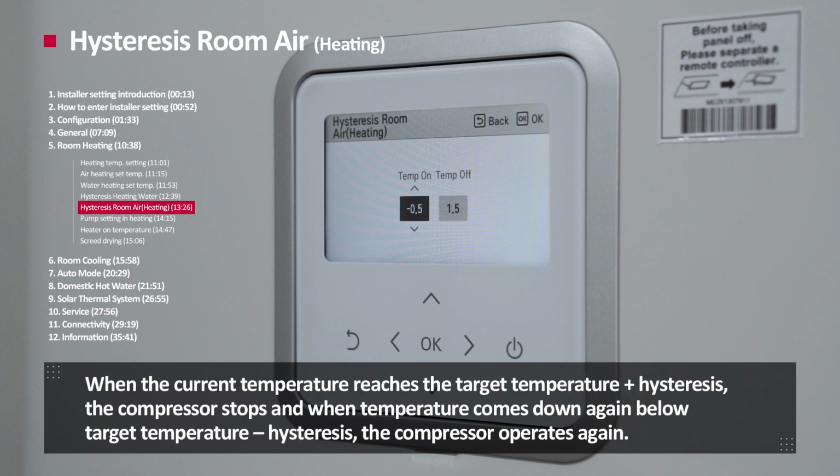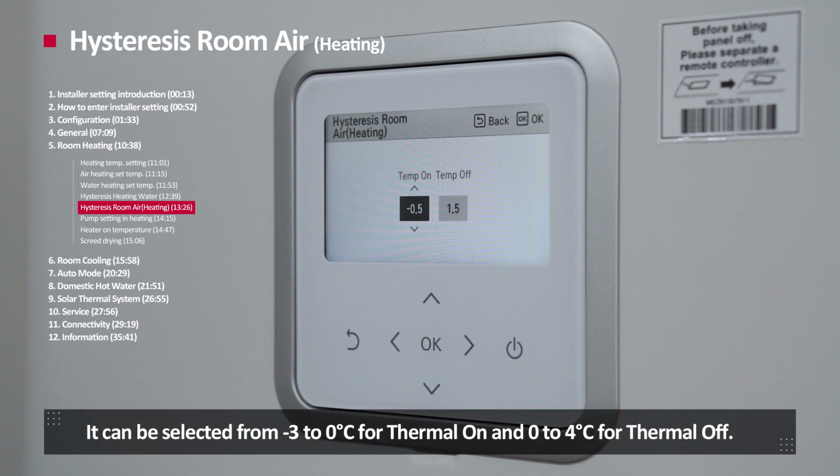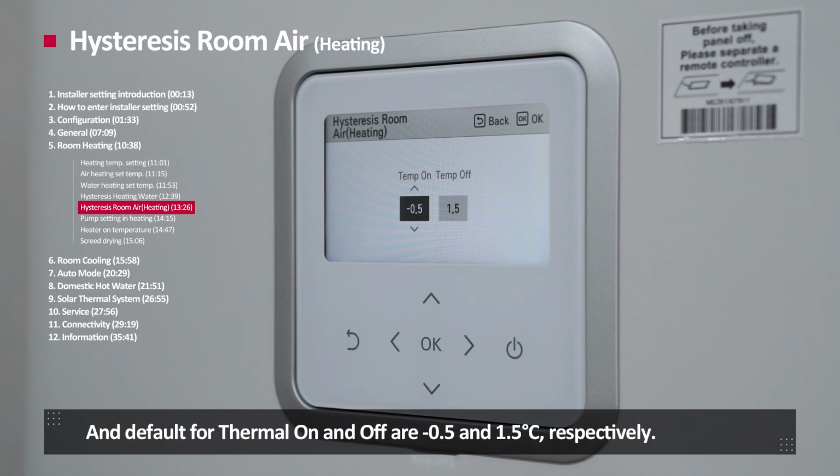When the current temperature reaches the target temperature plus hysteresis, the compressor stops. And when temperature comes down again below target temperature minus hysteresis, the compressor operates again. It can be set from -3 to 0 degrees Celsius for Therma on, and 0 to 4 degrees Celsius for Therma off. And default for Therma on and off are -0.5 and 1.5 degrees Celsius respectively.